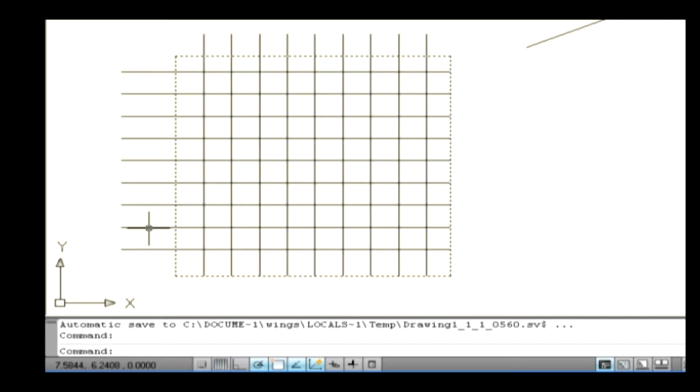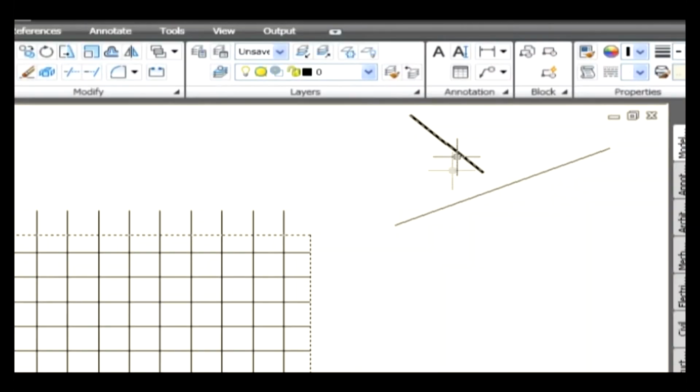Edge. It has 2 options. Extend allows the line to trim in an imaginary fashion by extending the line to get intersected. The No Extend option does not allow the line to extend in an imaginary fashion. For example, draw 2 lines perpendicular to each other, and they shouldn't touch each other. Go to Modify tab and select a Trim icon.